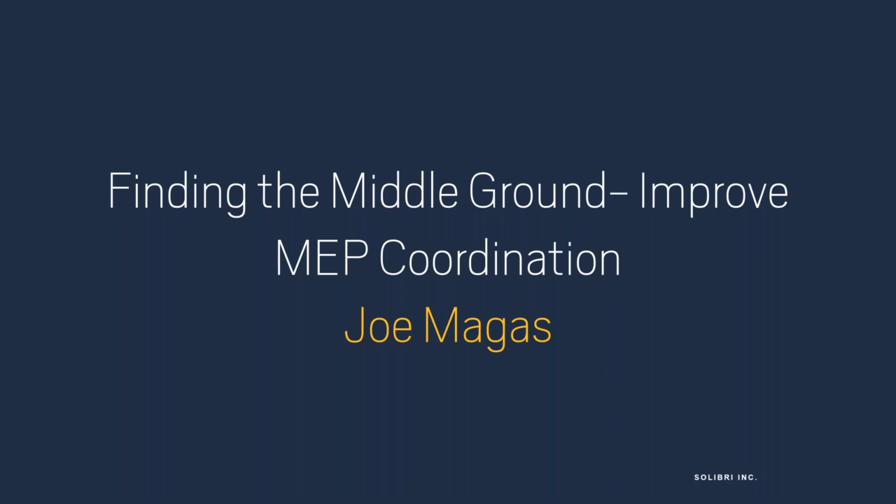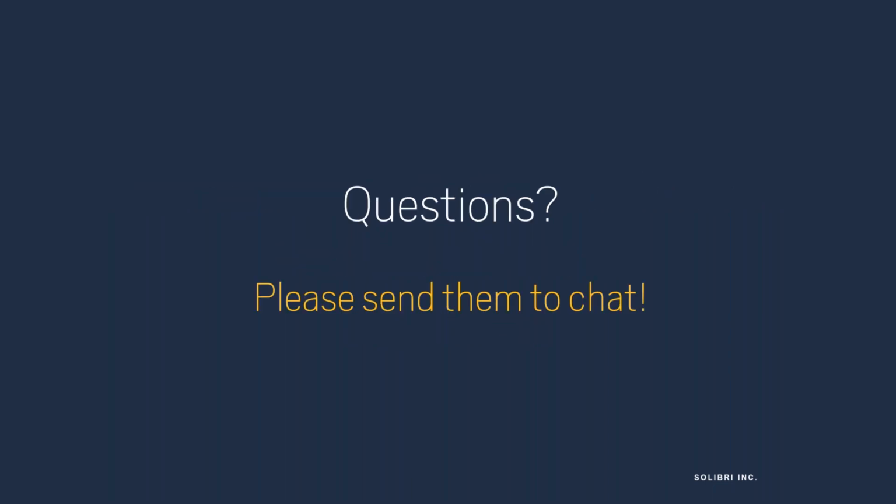what Joe touched on was classification of water closets or men's rooms or women's rooms or whatever you want to call your toilet rooms, is that you can bring in additional information to make a more intelligent model within Solibri. But I don't know if you can really get that information back out. We don't really have a connection up to, say, Revit or ArchiCAD to then take that information and stick it back in. But yeah, it's my understanding it's deliberately not there.